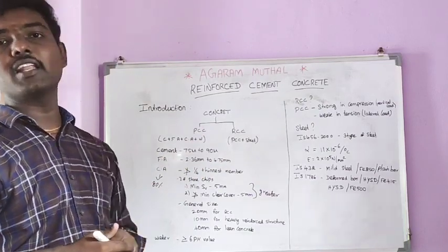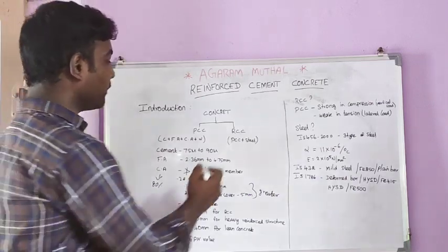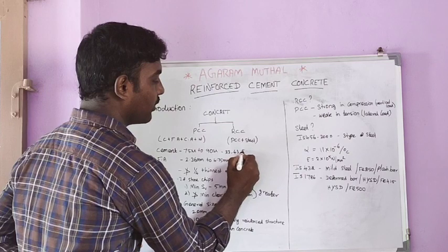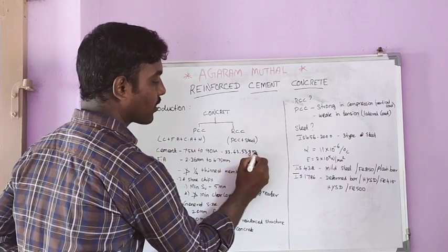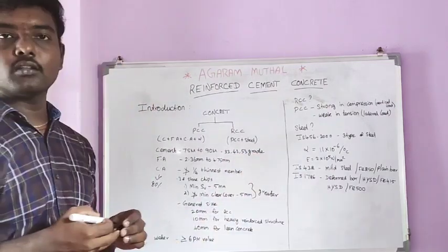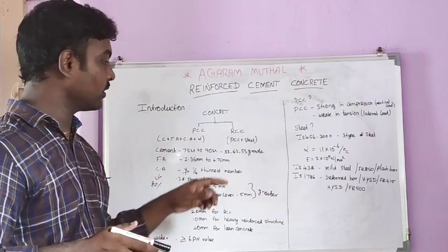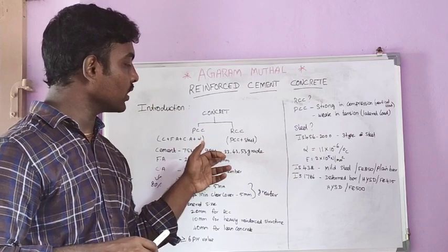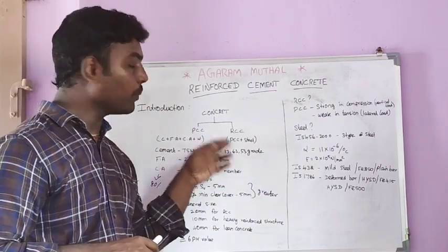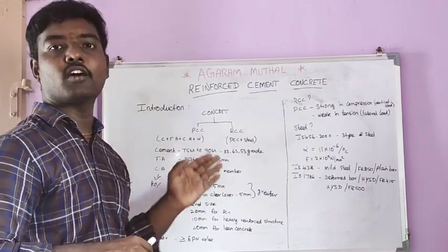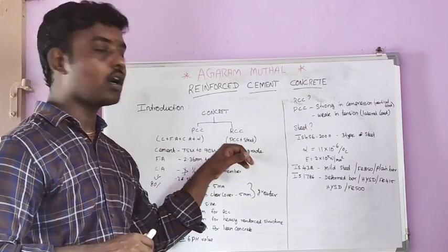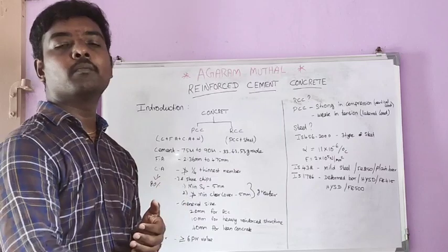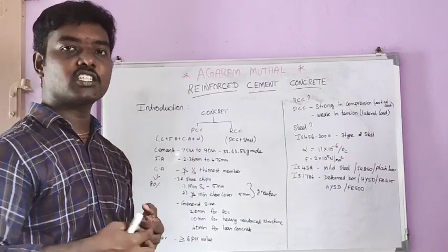The grades of cement generally available are 33, 43 and 53. Nowadays there is no 33, 43 is available only for laboratory purposes, and all shops have 53 grade, even that containing fly ash content.